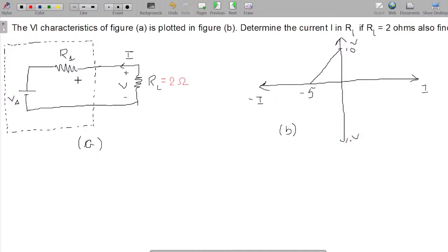Okay, is there anything more in the question information? No, there is no other information. We are asked what is RS, right. Now again going step by step, right. First, when I equals 0, when current in the circuit would be 0, would the terminal voltage, this V, equal Vs? Because again we are talking about an open circuit. So when V equals Vs, when would such condition be? When I equals 0, V would be equal to Vs.